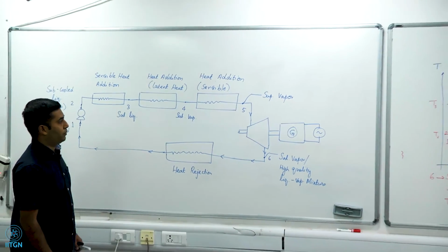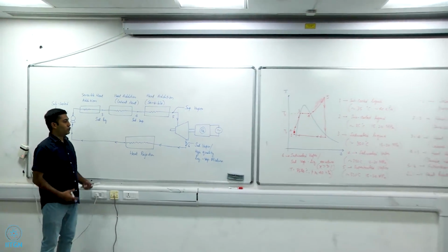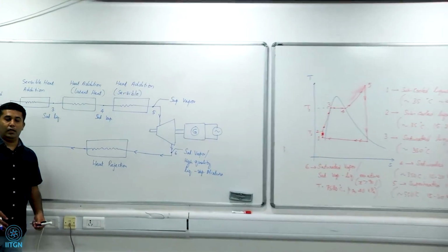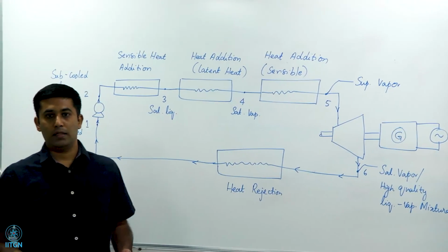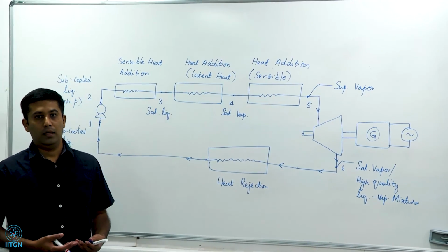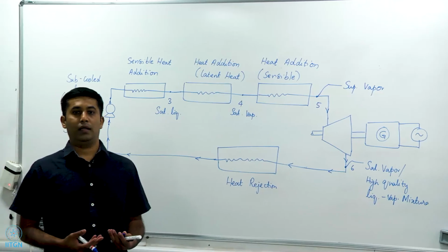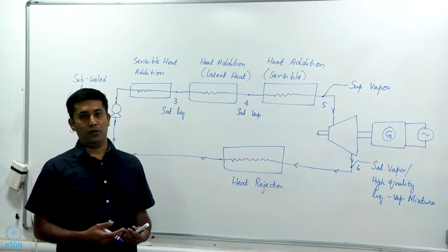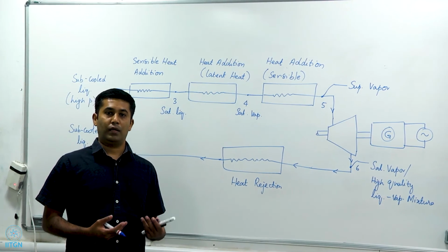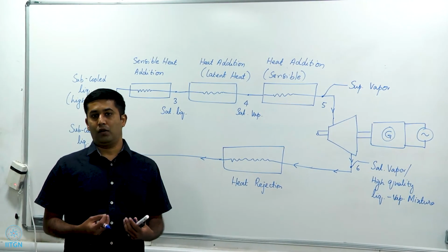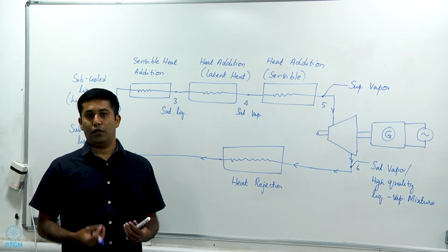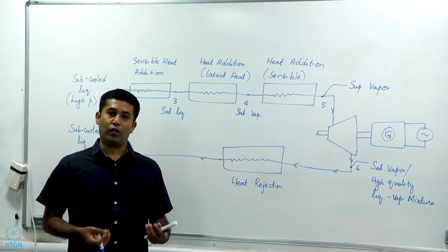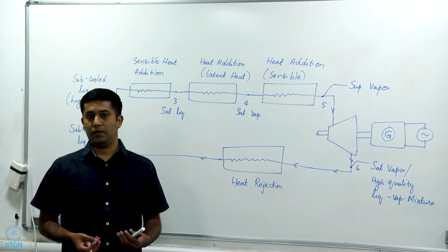So this is how a Rankine cycle operates, and most of the electric power that we derive today is from this cycle. And of course, there are many advantages as well as disadvantages of this cycle. One, we use fuel that is considered to be very dirty because it creates a lot of pollution, not just in terms of carbon dioxide, but also in terms of particulate matter, in terms of sulfur and phosphorus and mercury emissions, all of which are very harmful to the atmosphere, to the water bodies, as also to the soil around us.